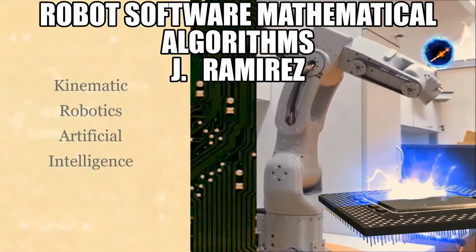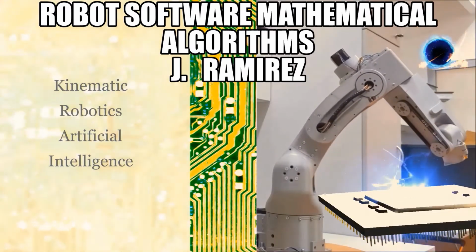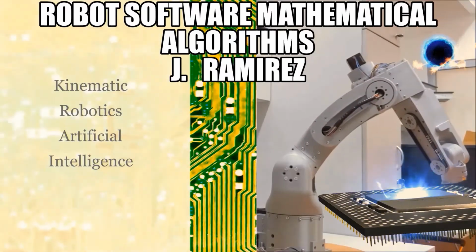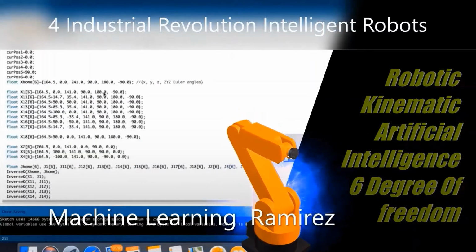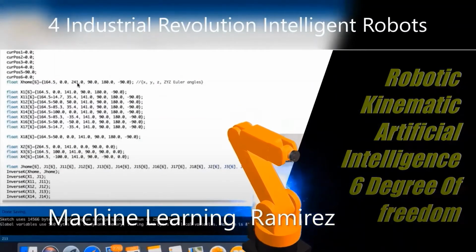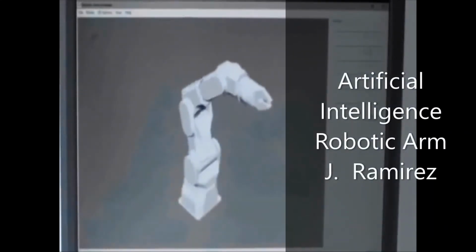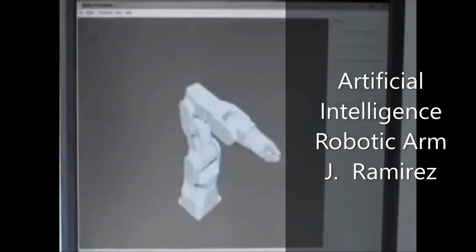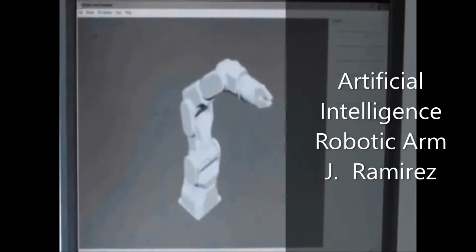During the initial autonomous operation, the robotic arm takes the initial start position of the program. Then the arm takes the measuring position according to the study performed for the IR sensor. As the arm reaches the measuring position, the infrared sensor starts to collect distance measurements between the eye of the sensor and the sorting area.